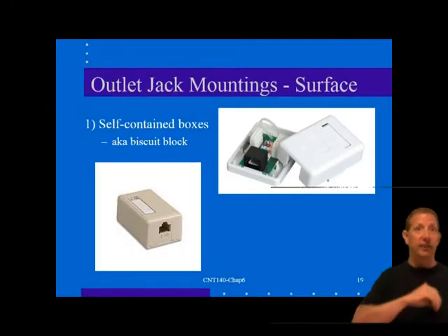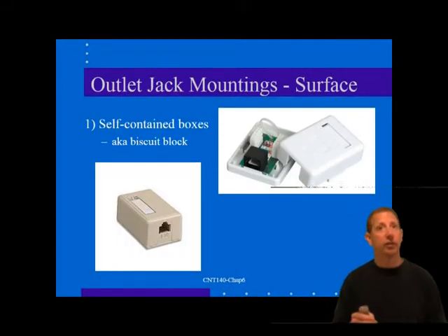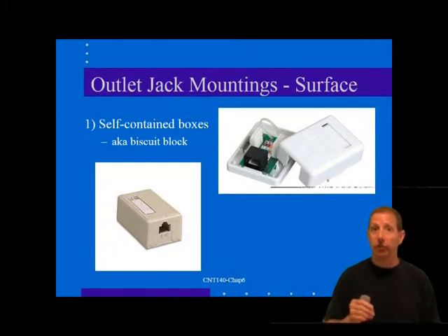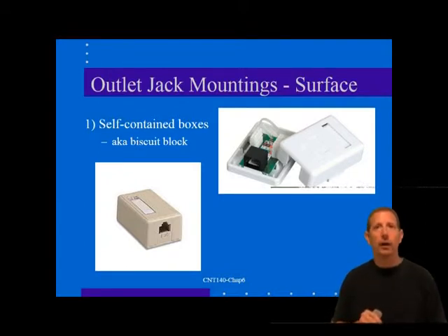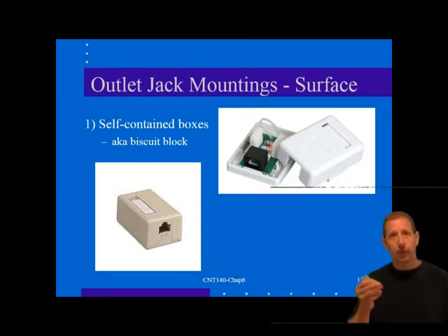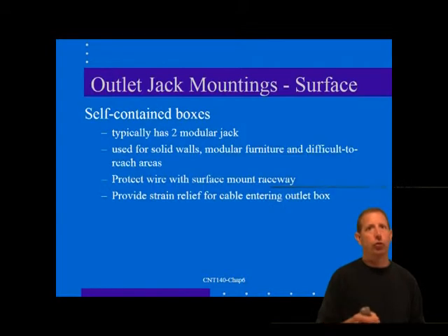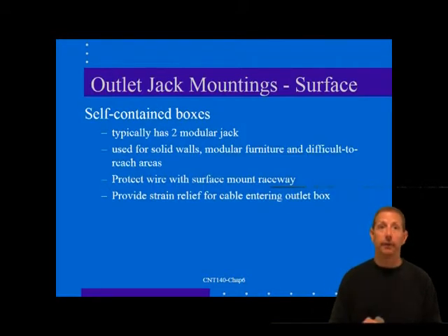The 568-A standard calls for two circuit links to each workstation, but leaves the use of the links up to the user. Both should be fully wired, 8-position RJ-style modular jacks or appropriate fiber jacks to satisfy the standard, although you may wish to make one a 6-position RJ11 style jack if your telephone system calls for that. This is particularly appropriate if you choose to totally separate the telephone and data wiring, as we discussed earlier.